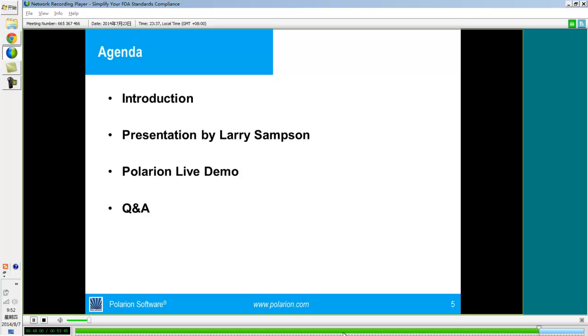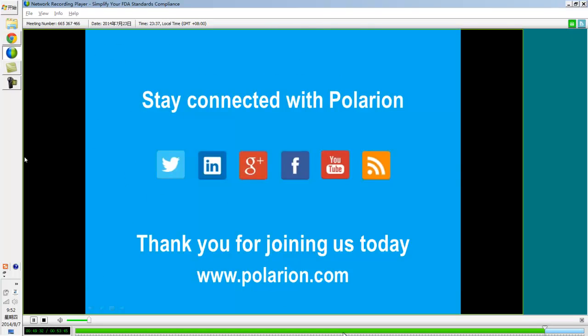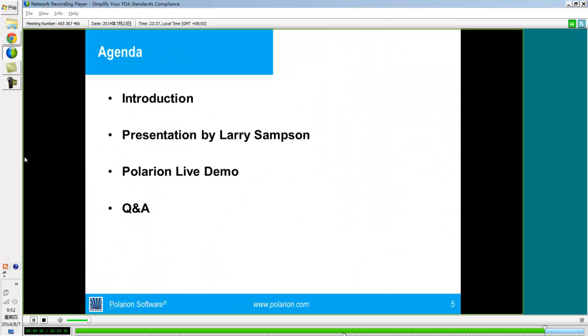Yeah, so essentially I think the difference is that the harms evaluation is a top-down fault tree analysis, more of a view of it, whereas the failure mode effect analysis is a view coming from the bottom up typically. So if it's a design failure mode analysis, we'd start with the component and go to the functional description of the component, and then that would lead us to things that could go wrong. So you'd say we have a brake assembly. The functional description of the brake is that it stops something. Well, what can go wrong? Well, we can have a design that's too weak. When the doctor pushes it, it breaks the design. So we want to do some kind of mitigation against that. So it's really a bottom-up approach.